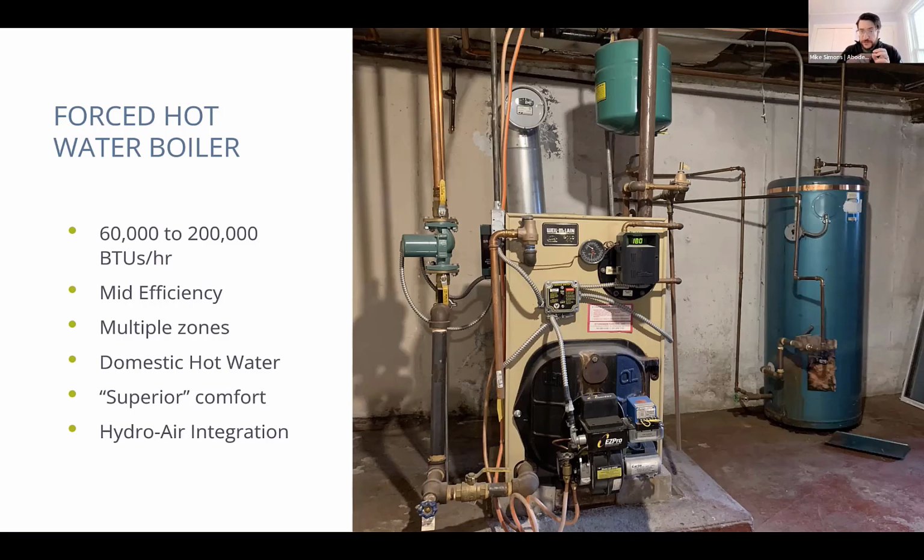However, let's say that this boiler is in an 80-year-old home, there's baseboards throughout the home, and they've gone through a deepish energy retrofit. It's likely that this temperature could be way, way lower because the load has gotten way lower. Then, if you adjust the aquastat and get through, say, winter number 1 with 140 degree water, you could feel very good about adopting an air to water heat pump system.